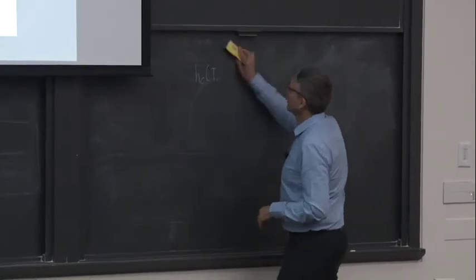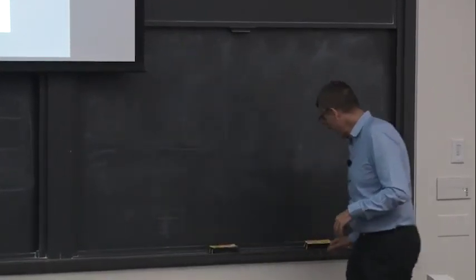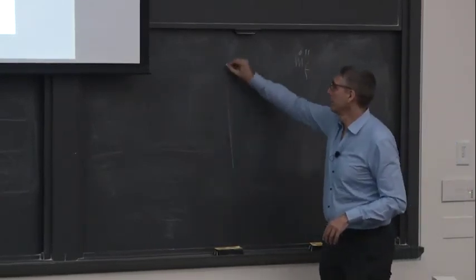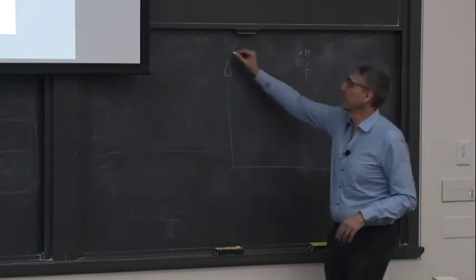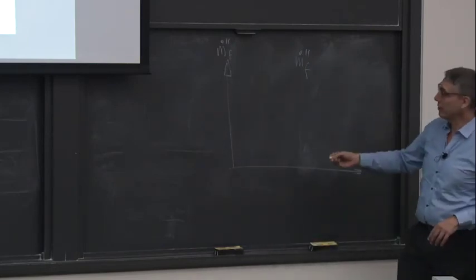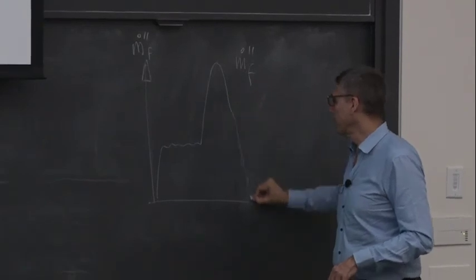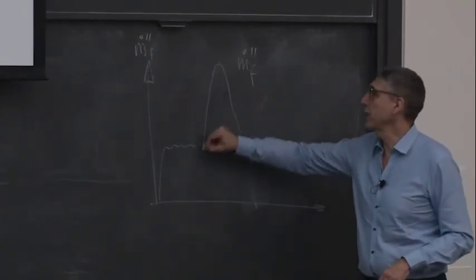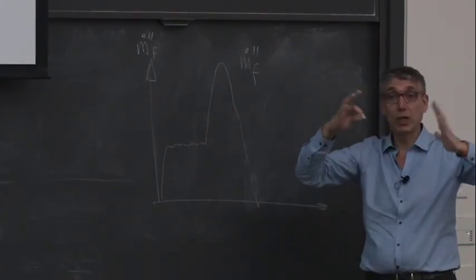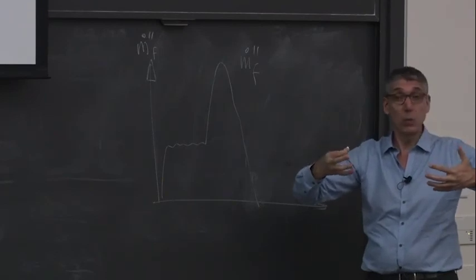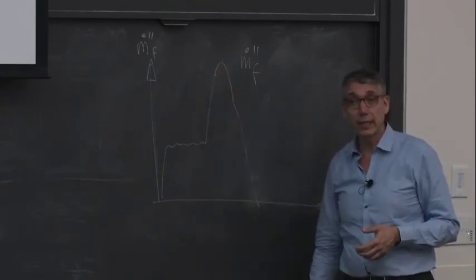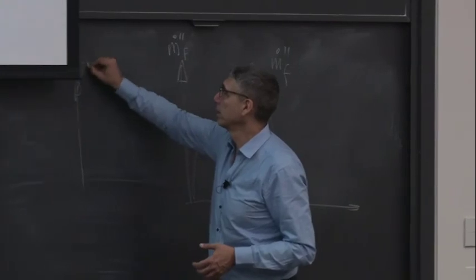So that's the heat release rate per unit area. How would m dot double prime look? Exactly. Not almost the same. It will actually look exactly the same. No? Because effectively what you have is this, and it goes like this. This will look exactly the same. Because once it changes phase, what you have is a much higher evaporation rate. You have the same feedback because the flame is not changed very much. And effectively, you need a lot less energy to evaporate. So your burning rate will actually look like this. So how would your heat of combustion look?